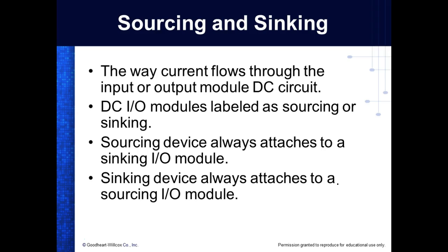Now, if I've got a syncing input, I better buy a sourcing sensor, right? Because sourcing means it supplies the plus. Syncing means it supplies the what? Minus. I understand that.